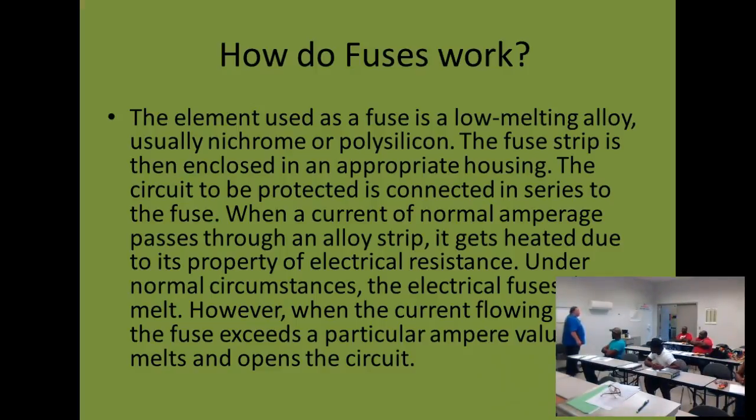At first, they started putting batteries in these. Some people don't like doing batteries, so you can either use batteries or run a common to it. So you got 24 high and a common. Right? Because what does a load need? You got light in here or digital. What does it need? It needs power, that's right. And one leg of power is not good, right? You got to have the other leg, right?